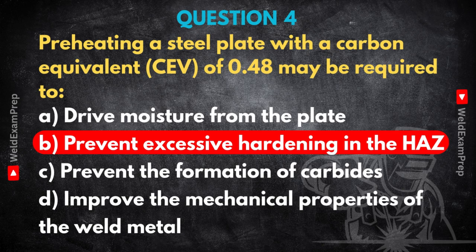They need to verify not just that the minimum preheat temperature is reached before the arc is struck, but often that it's maintained during welding, especially for multipass welds or thicker materials. The WPS will specify the minimum and sometimes maximum interpass temperature too. So it's not just a quick check at the start, it might involve monitoring throughout the process.